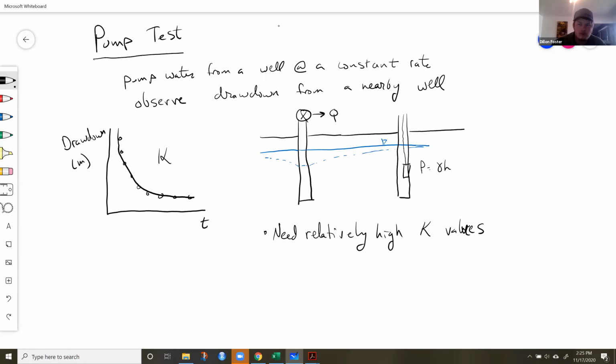Like very porous. Porous. So what kind of substances, what kind of things in the ground are porous? Like sand, cobble. So alluvium, do you guys remember what alluvium is? It's the stuff brought down from rivers: sand, cobble, gravel. Alluvial aquifers next to the river made of river sediment often have very high conductivity values. Maybe limestone, I'm not quite sure, it's a porous kind of bedrock, could have high conductivity values.